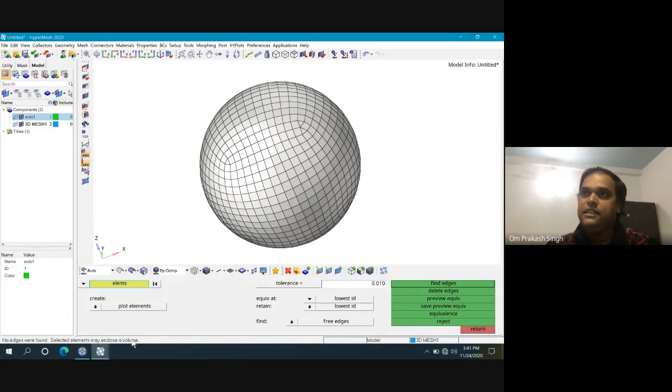But just in case, let's say you are doing a very complicated geometry, let's say the interior of a laptop, or a lot of components are there, or a building simulation or an aeroplane simulation. When you import the geometry, some geometry information will be missing. So even if you create the surface mesh, it will not be a closed volume. So your first target is to stitch, पैचिंग करना है आपको, otherwise वो आपसे नहीं हो पाएगा।